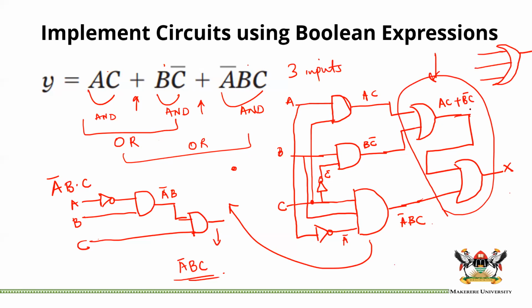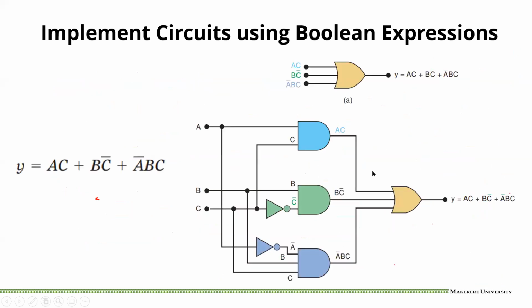So I was saying that if we don't have a 3-input OR gate, we can use two 2-input OR gates to do the same operation. Yeah, that's a good question. So that I do not confuse you, this is actually the final term, which is what we have done, only that here now we have a 3-input OR gate, which is what Pascal has just been asking about.